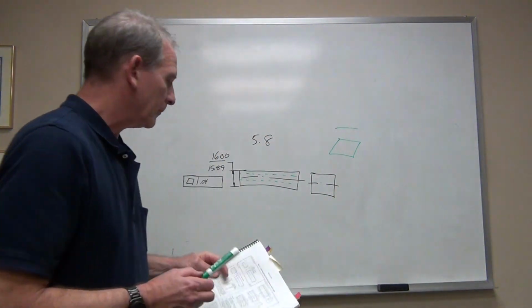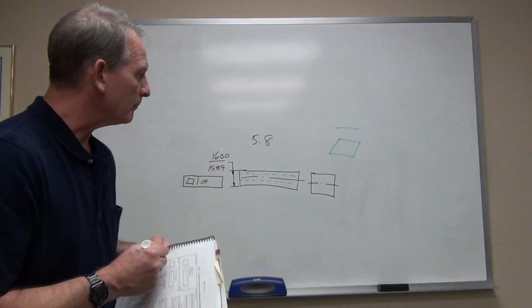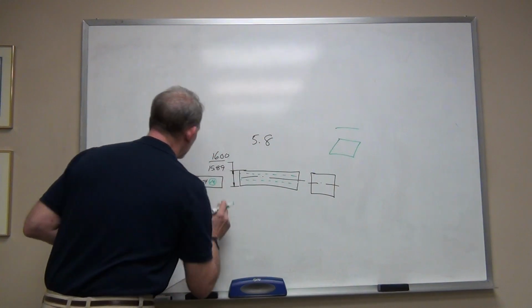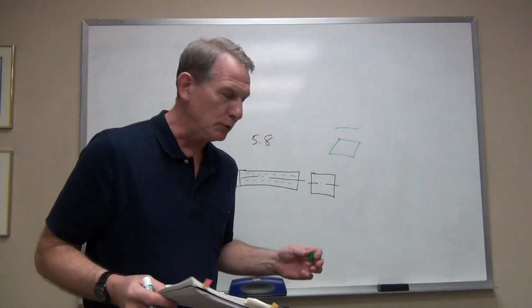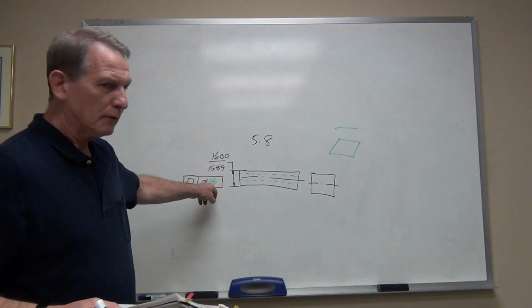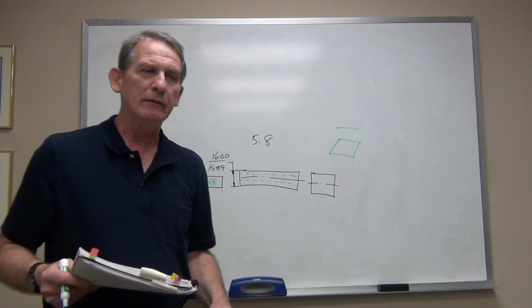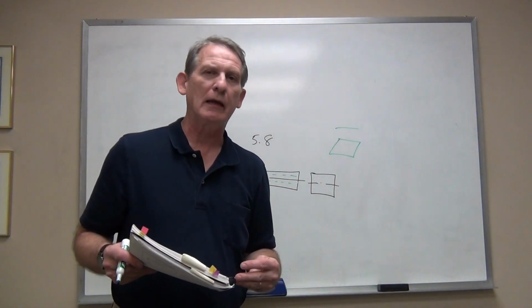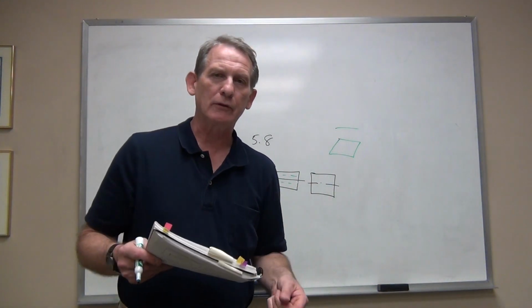Okay, and then now just again, very similar to what we saw before. We can apply a material condition modifier to the feature control frame, and that allows that tolerance zone that is controlling the derived median element of that bar to adjust its size based on the material condition of that bar.